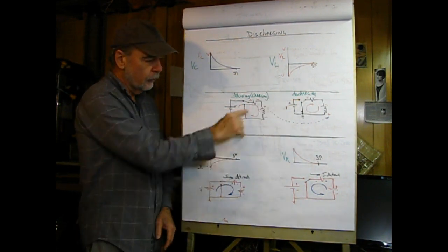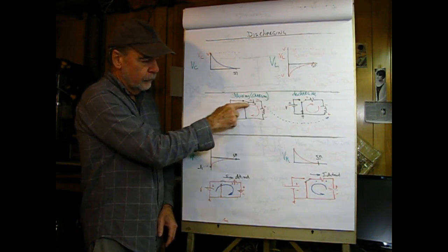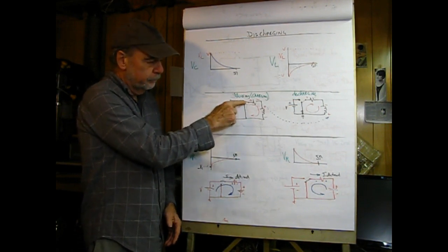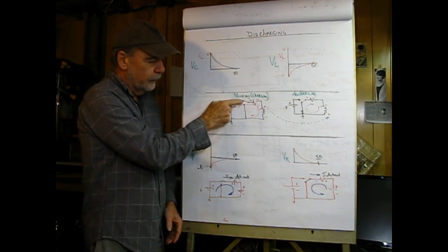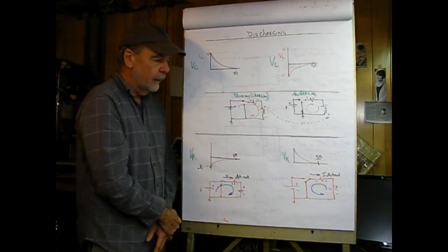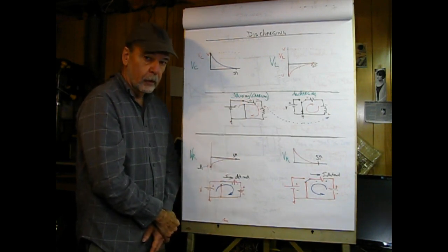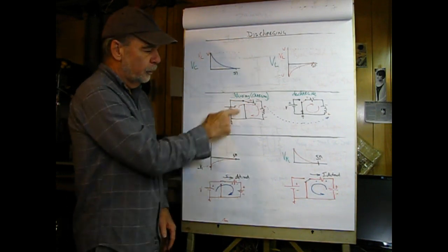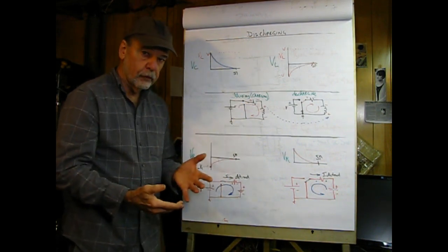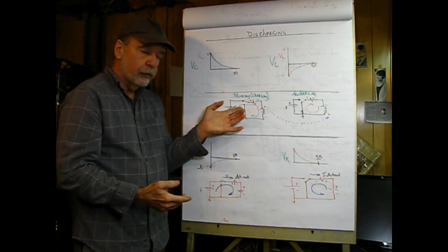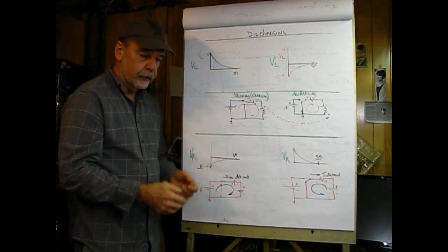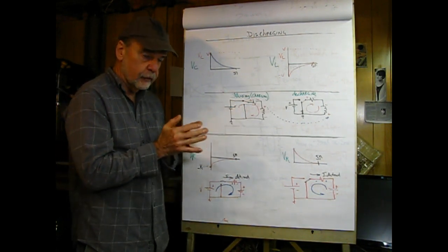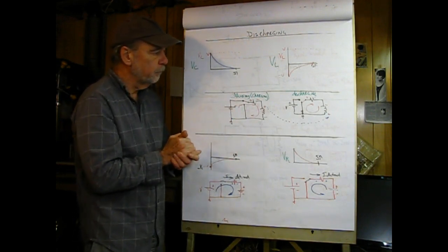So when you see a single bat and a single common, and 2 poles out here, it's single pole double throw, abbreviated SPDT. And this would be, just for familiarity's purpose, like a 3-way switch in your house where you can turn lights on and off from 2 locations. It would be a switch like that.